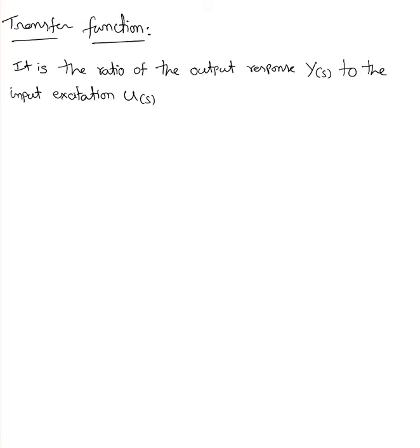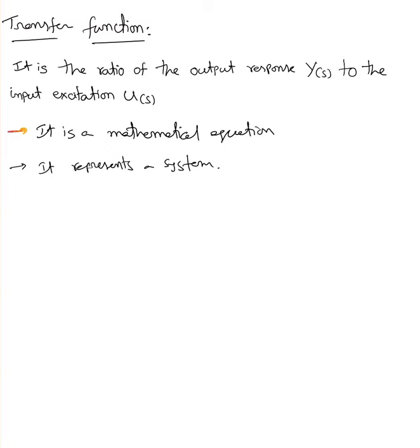In this video, I'm going to talk about transfer function. So the transfer function is a mathematical equation. Basically, it represents a system. Another definition for a transfer function is it is the ratio of output response to the input excitation. So as I mentioned, any system I'm going to represent with h of s.